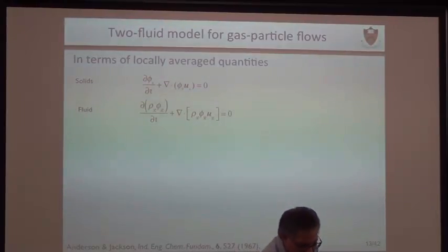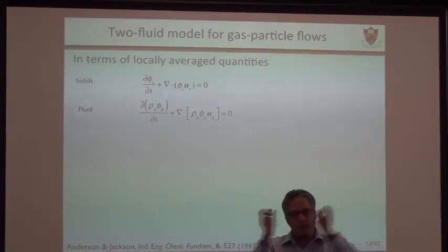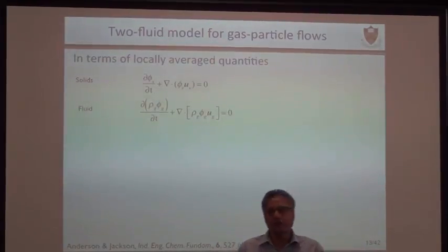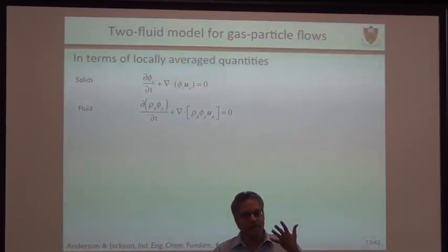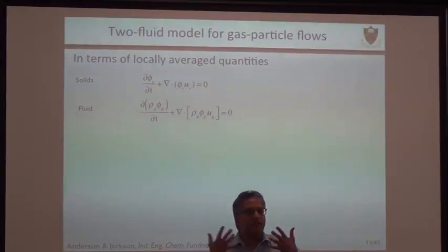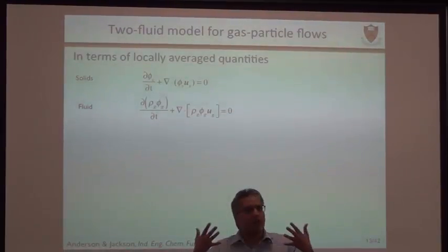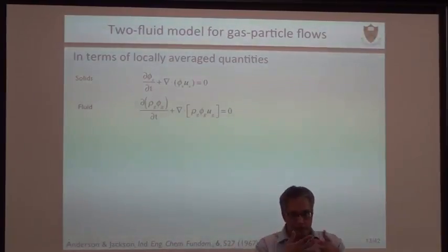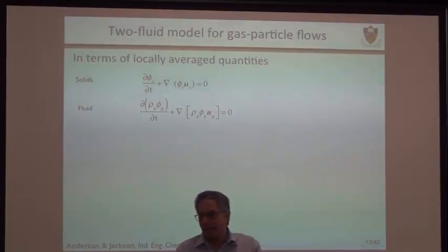The main theme of looking at the large scale flow problem is this. You have all these particles that are colliding with each other, and they are transferring stresses through each other. So we can begin to pretend that we can treat that as a continuum phase. We treat the particle phase as a continuum, and then we treat the gas phase as a continuum, so you have an interpenetrating continuum. You have two phases that are flowing together, and they're competing for volume, because one can't occupy the volume occupied by the other. So you have to share the volume between them.